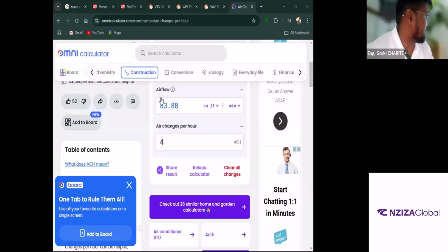That brings us to 80 to 85 CFM size for our VAV box serving that patient room. Is that making sense now? Now this is the total air changes per hour. This also contains that 41 CFM we were talking about for the minimum outdoor air. Total is a sum of the minimum outdoor air changes per hour along with the air changes per hour that are required for taking care of the loads. Does that make sense?